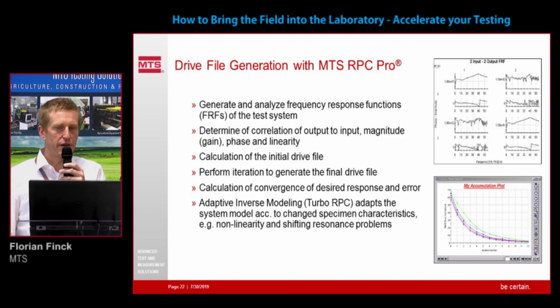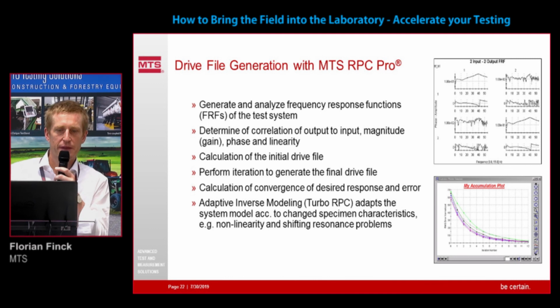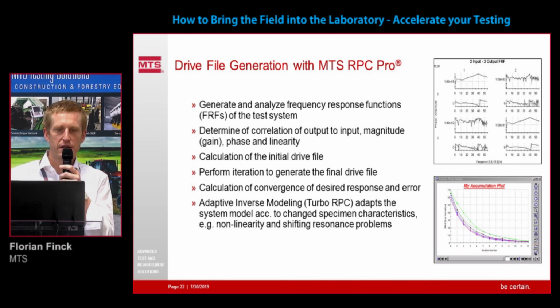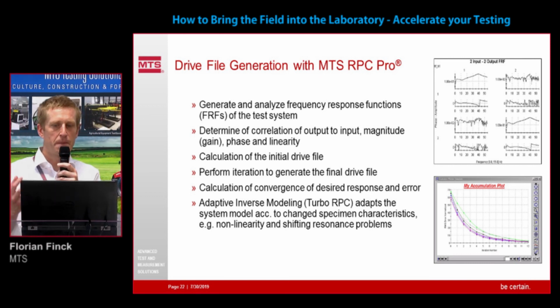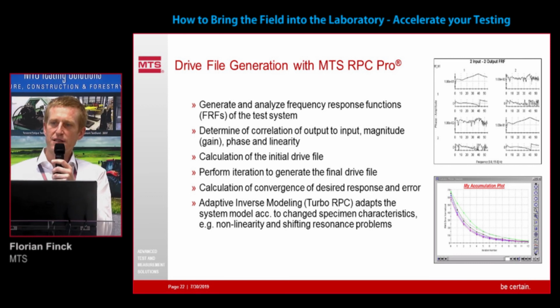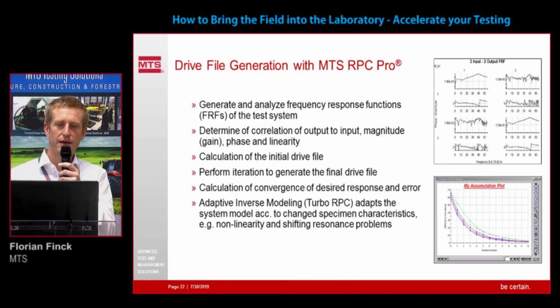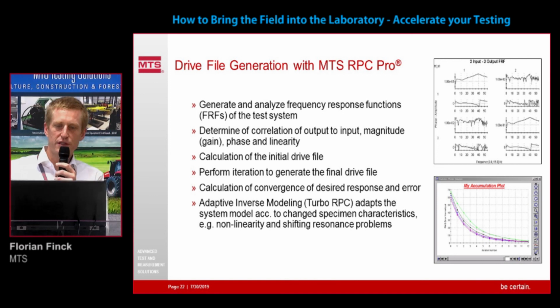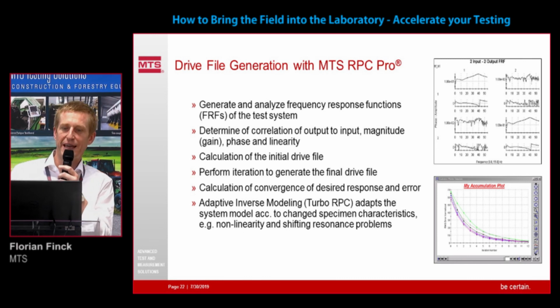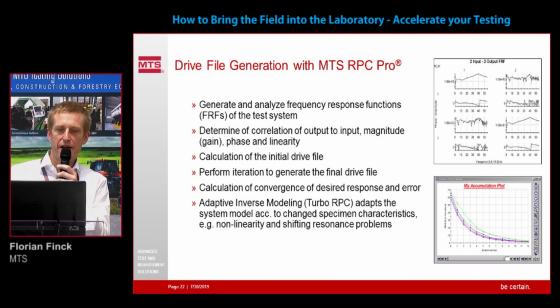The drive file generation with RPC: we are generating and analyzing frequency response functions. We can evaluate the cross-coupling between different channels. We can determine the correlation of the output to the input, the magnitude and the gain, and the phase and linearity.